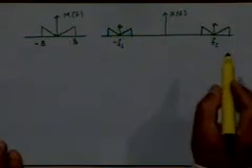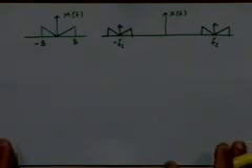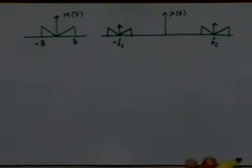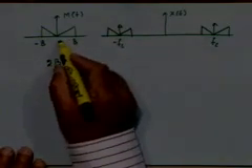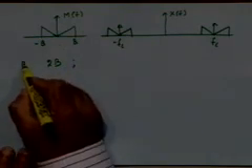In this case, we have a localized specific value of the carrier component along with the modulated signal, right? So the spectral properties of this signal are to some extent similar to those of the DSB-SC, in the sense that the bandwidth required is 2B as against the message bandwidth of B.